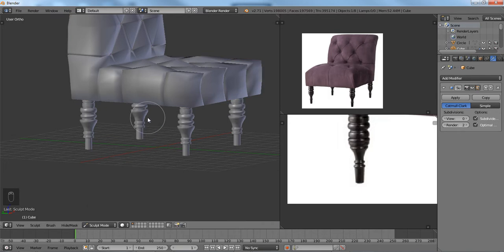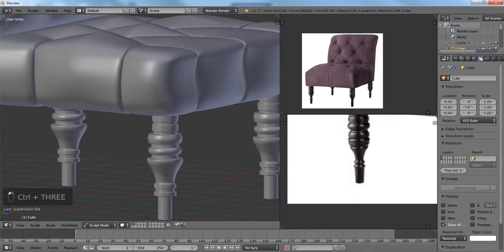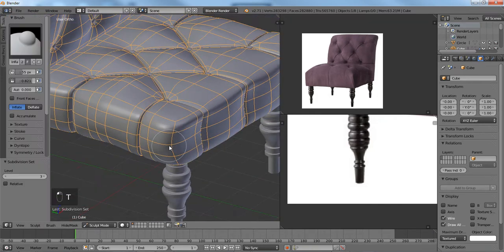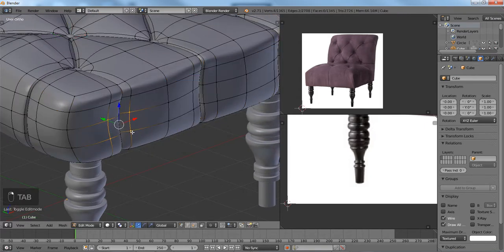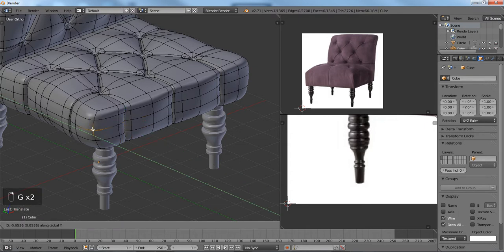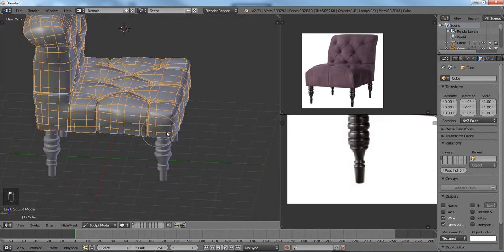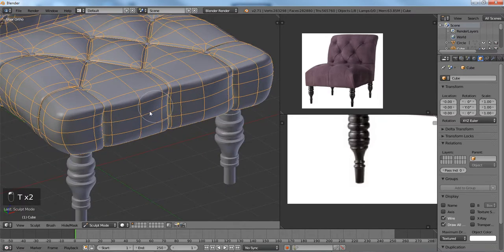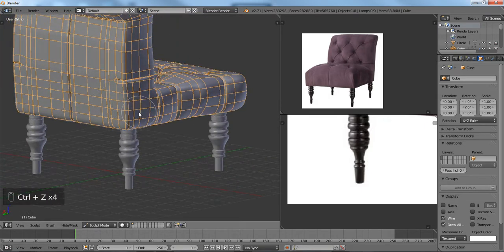So we're just going to go into sculpt mode, and we're going to increase our subdivision to about 3, and then we're going to enable wire, and pretty much with inflate. Hopefully if it works. Or our grab brush. I guess we can add some asymmetric detail to it, which I'm going to take off the mirror modifier to achieve that. Alright, and initially just keep going over certain parts of the chair that really need it.